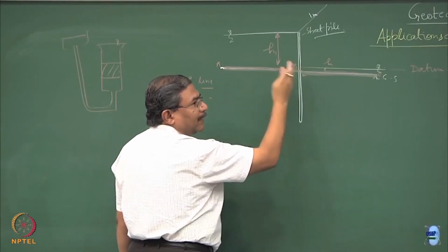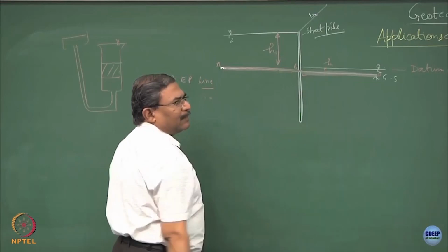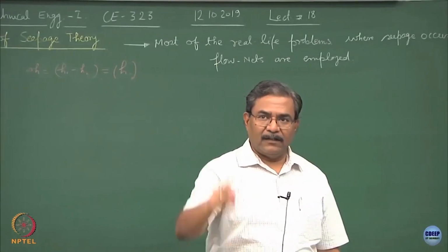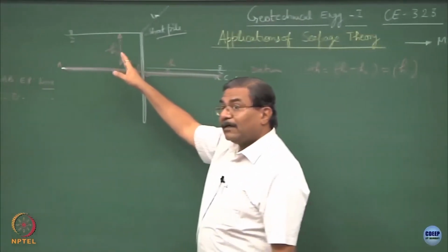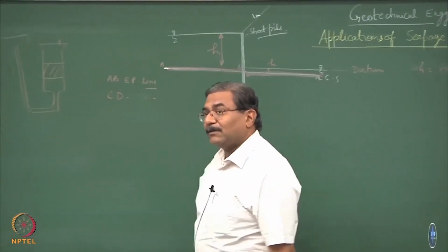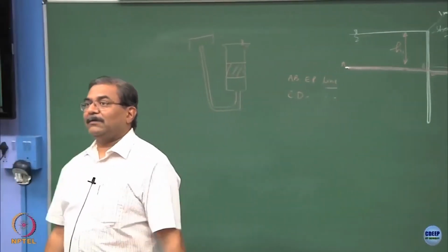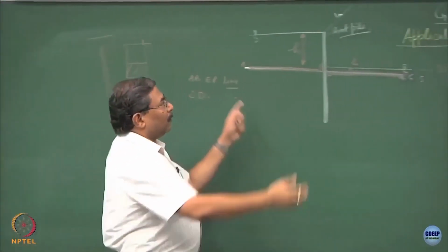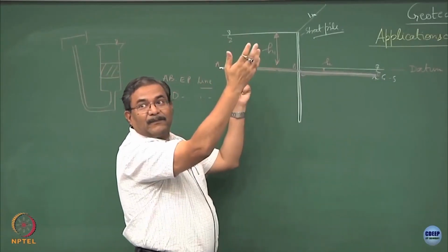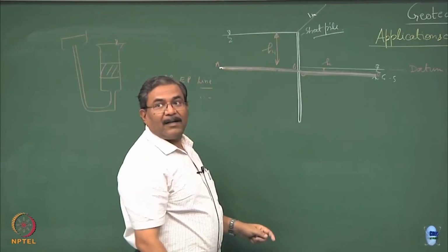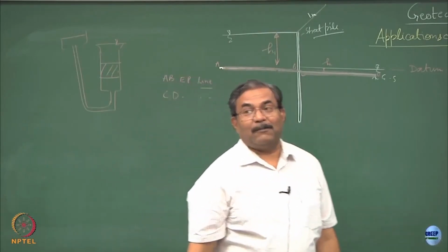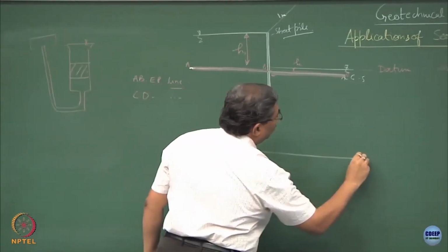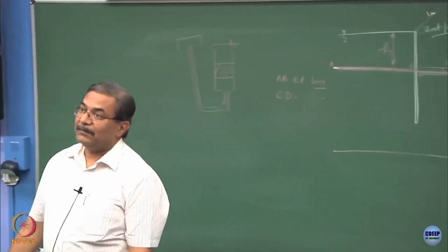Because just on the left hand side and right hand side, and I have been repeatedly saying the thickness of the sheet pile is extremely small, 1 inch, 2 inch maximum. So, you are correct. What I have done is I have created a head. Is creating a head a good thing for you or is it something which you have to be careful about? Both, yes, you are right, very good. One thing is you have created a facility, you have created a reservoir, clear. Second thing is you are inviting problems for yourself. As far as your foundation system is concerned, you have created a problem.